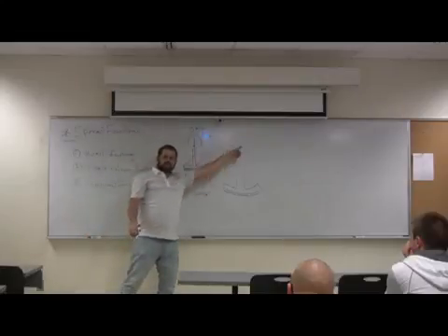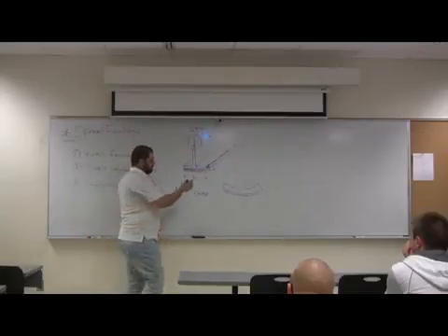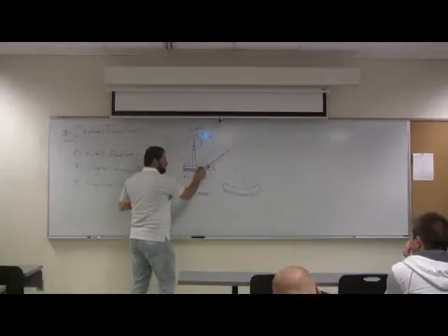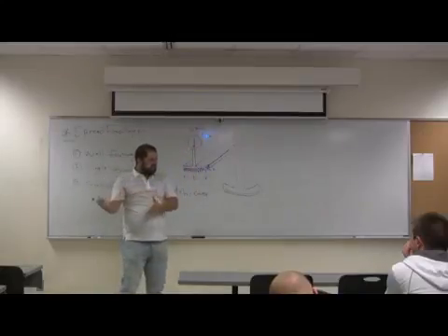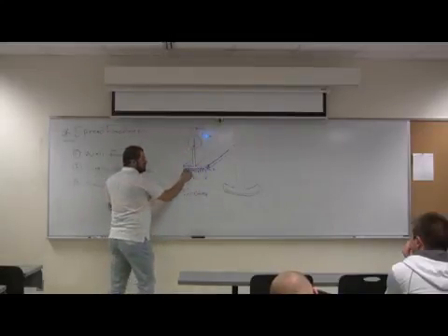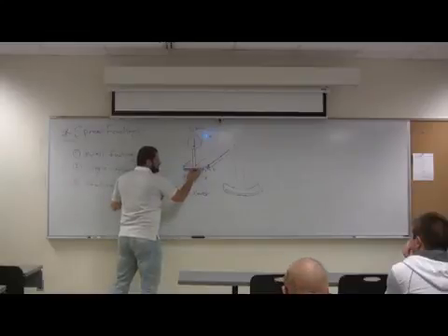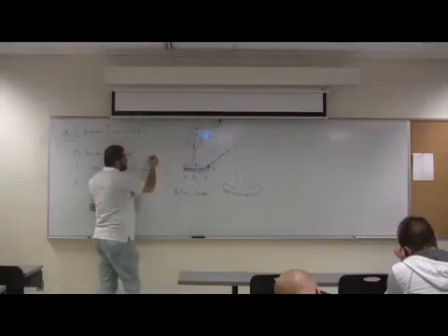Okay, so now what do we do? Do we put any reinforcement in the wrong direction? From whatever you have learned so far, you always need a minimum reinforcement, either a given value or shrinkage and temperature. So this is the shrinkage and temperature reinforcement. What's As for shrinkage and temperature in footings?